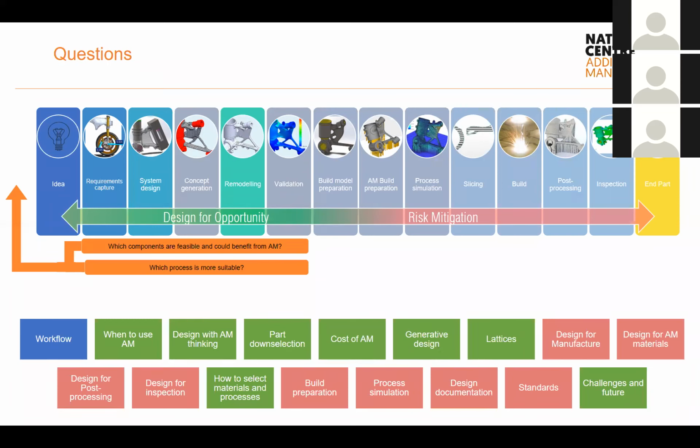So then we can use FEA software tools. Some of them have implemented both capabilities as well. But in reality, what we get out of the topology optimization usually is not the final part that we're going to produce directly, because we need to add some areas where we have fixed connections.